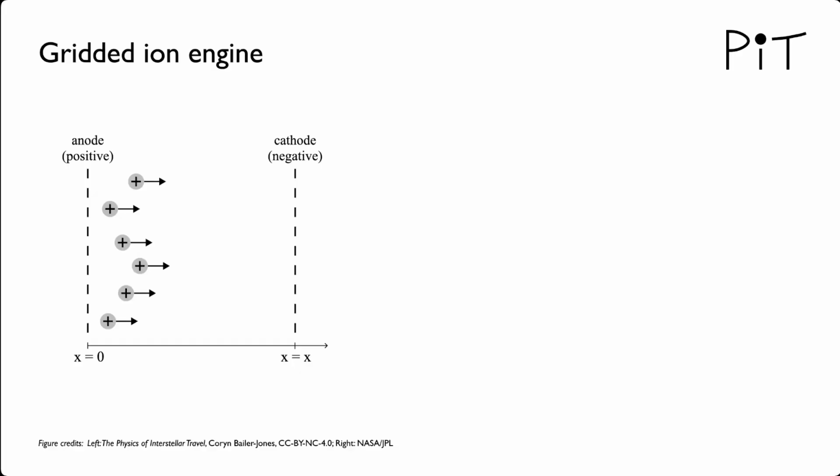In a thermal rocket, the mechanism for the momentum transfer is the collisions of the hot gas particles with the walls of the combustion chamber. In an ion engine, it is the electric field attached to the rocket pushing on the ions, equivalently the ions pushing on the field, that provides the momentum transfer. Although when you think about it, the interactions of hot gas particles with the walls of the combustion chamber is also governed by electromagnetic fields.